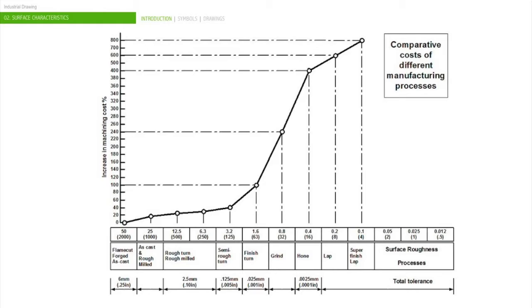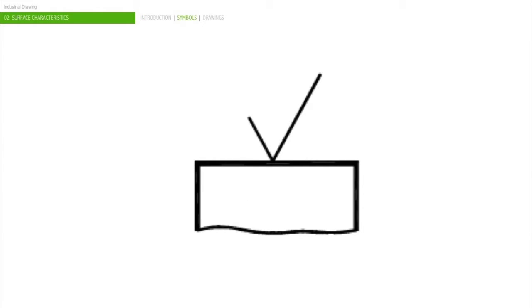This is the fundamental graphical symbol, and if it is used with complementary supplementing information, then no decision is taken as to whether removal of material is necessary for obtaining the specified surface, or whether it is not allowed to remove material for obtaining the specified surface.